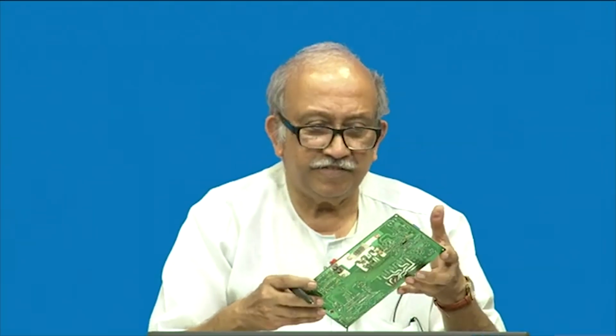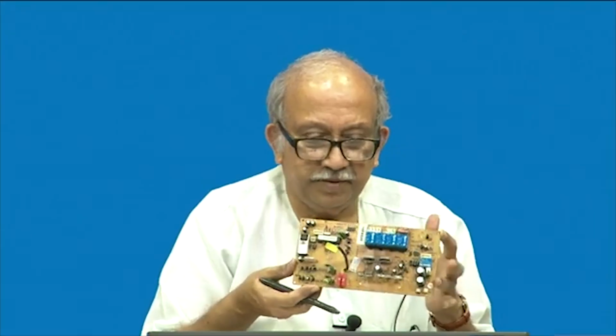Similarly, you have seen this, there are very large tracks, pads and all that here. All these large tracks and pads need to be reflected in your model. So, it helps if you try to start your solid model including these things like power components, while in the case of a routine small device they may not make too much sense.